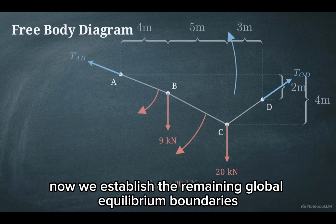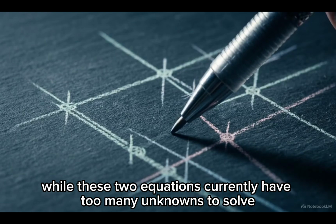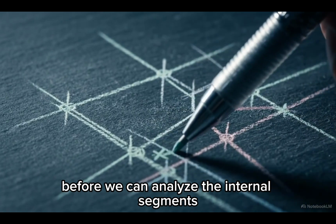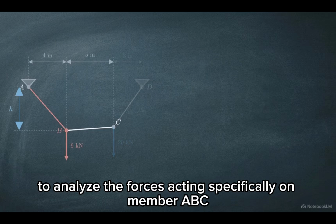Now we establish the remaining global equilibrium boundaries by writing out the sum of forces for both the horizontal x-axis and the vertical y-axis. While these two equations currently have too many unknowns to solve, they provide the necessary framework we need before we can analyze the internal segments. To find those internal values, we use the method of sections. We virtually dismember the cable to analyze the forces acting specifically on member ABC.